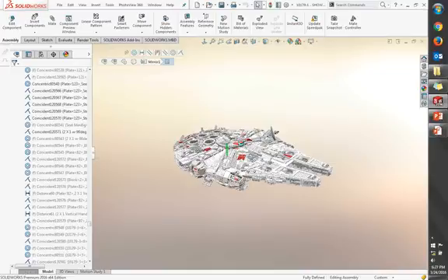So now what you're doing is you're leveraging SOLIDWORKS to know how to look in this big list and unsuppress something. So the basic steps here: I went to the sub-assembly that it was connected to, went to the other sub, and then I got to the part, right-clicked on the part, floated the part, edited the feature, moved it one over, and then I went fix, all the way back up. Something that I thought was going to take me a good half hour took me less than 5 minutes to actually get done. So I thought it was actually pretty beneficial at that time.